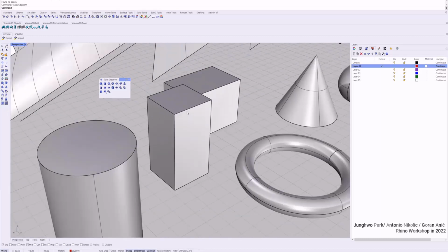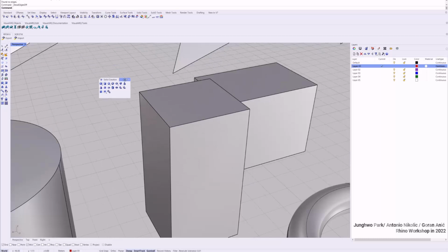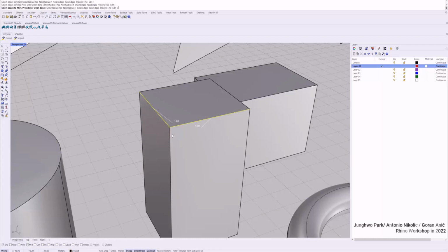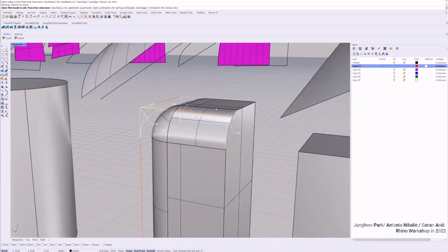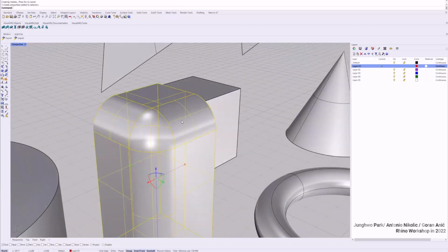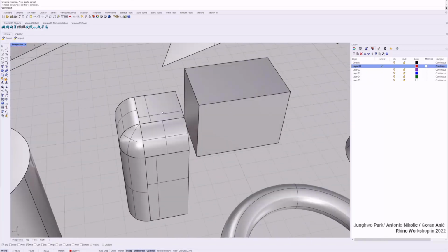And when it's a solid object, it becomes interesting, because if I go to editing solid objects, for instance, we can use fillet edge, define how much radius you want to give, and of course preview it. When you finish, that's your filleted edge. So you can completely fillet this kind of solid.